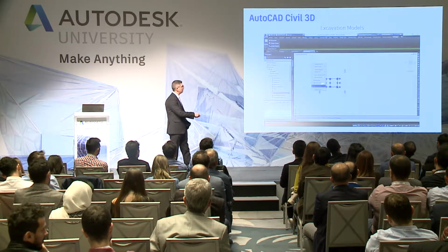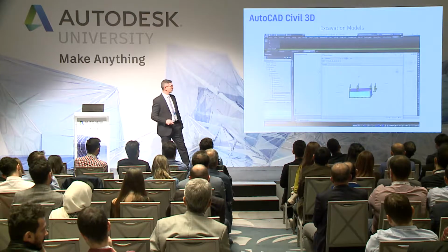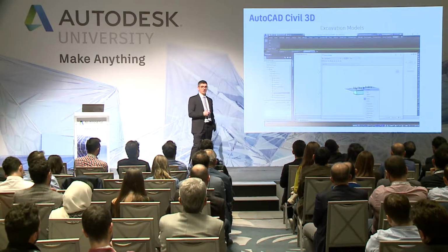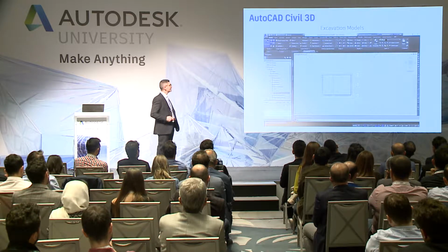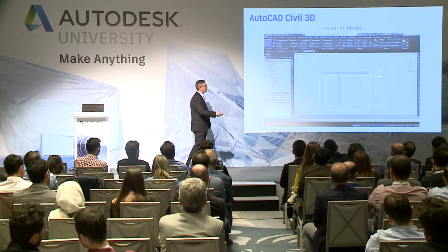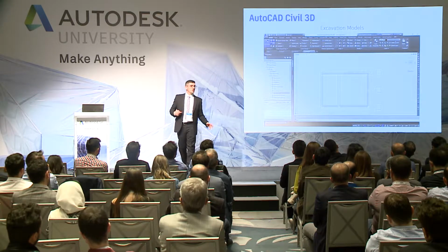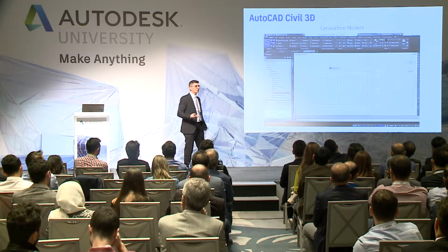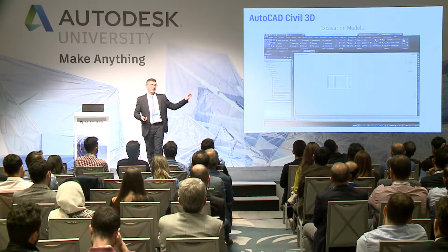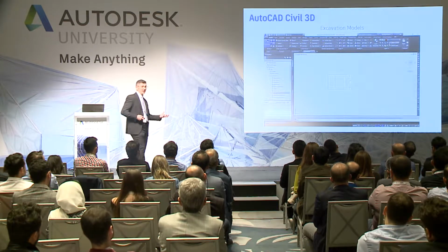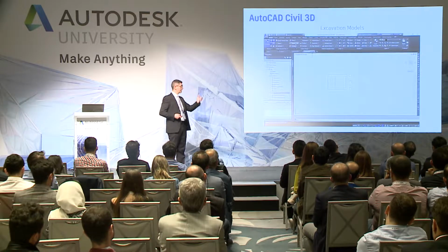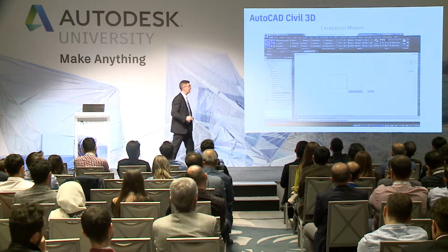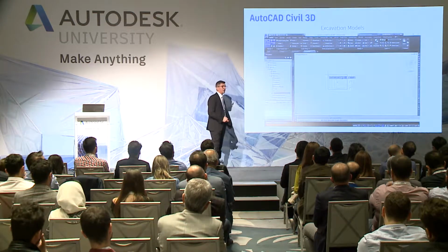And then if I see what happened, I am in this condition. OK? Then I want to create the excavation model for this type of special building. The second step is to define the element of Civil 3D that can allow me to manage the excavation. This type of element is the feature line. The feature line is a sort of 3D polyline that Civil 3D manages with different styles, and we can manage it from several activities. I have switched off all the elements that I don't want to use. Then I also have the structure for the foundation.